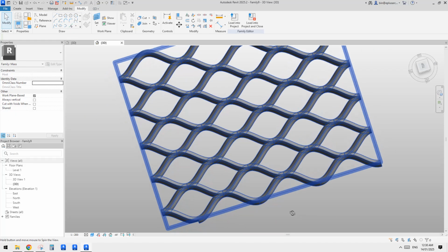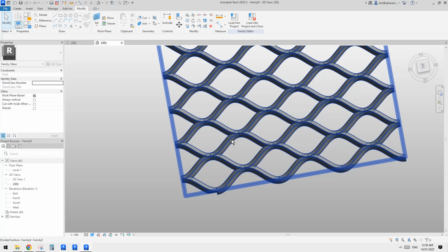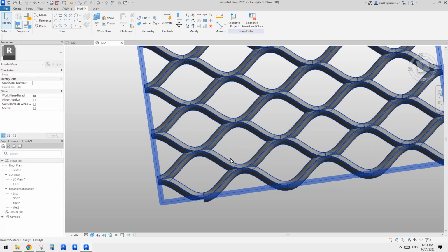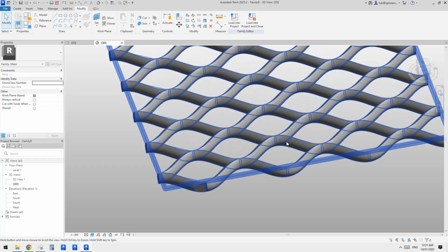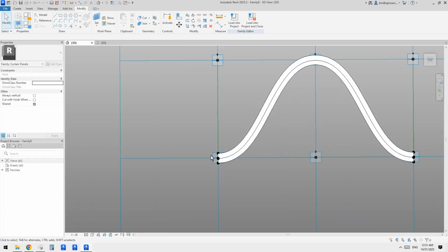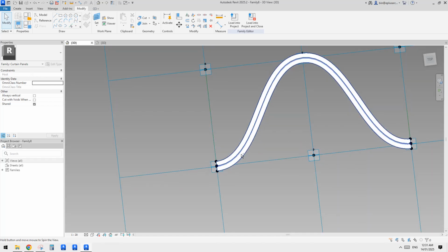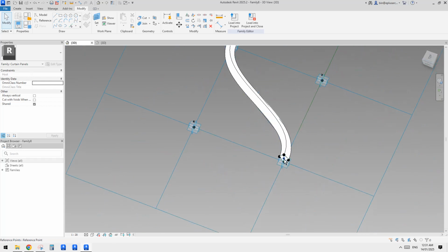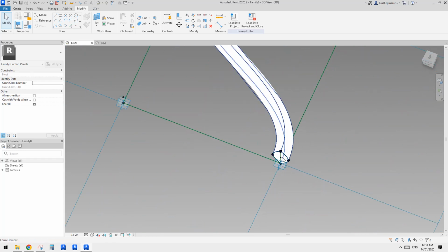Looks like we have some issue here when we do this, okay, so yeah, looks like we need to offset. I think that's easy to fix, because when we do this profile, we directly use this one, which means we need to consider the width, the offset 2, which is a half of this one.